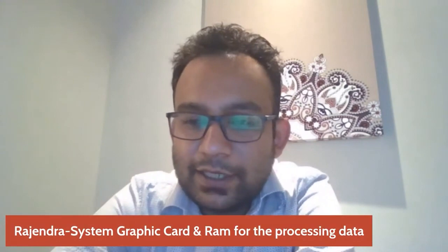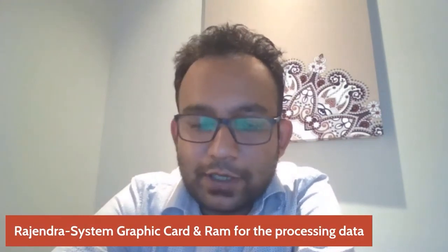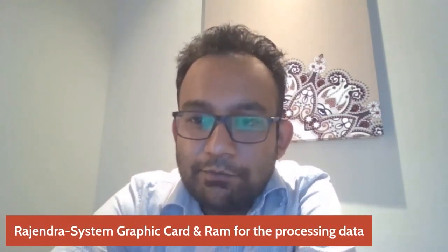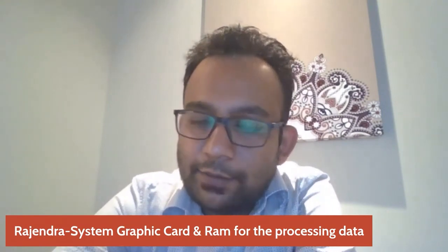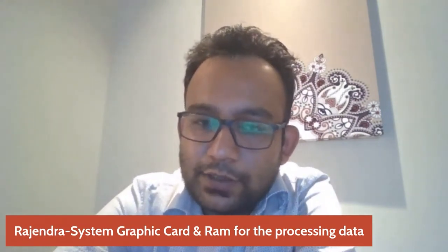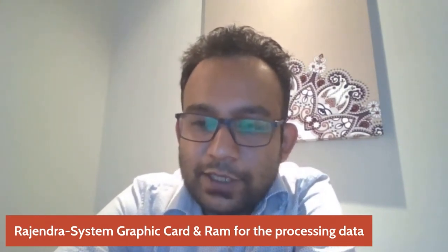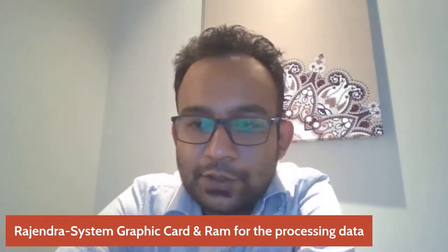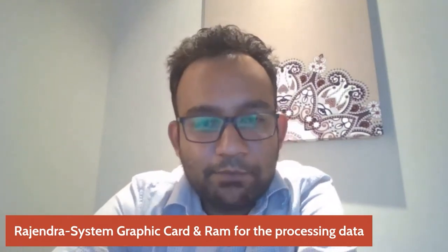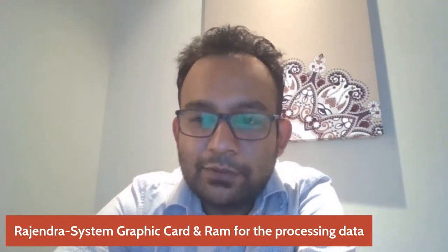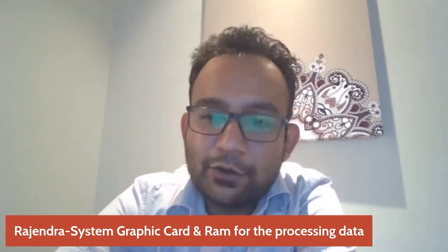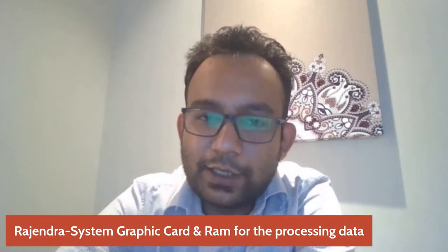Yes, Rajendra, that's a good question: system, graphic card and RAM for processing the data. So Rajendra, my recommendation is to get at least an i9 or Intel Xeon based processor. It should be a multi-core processor, and I recommend a RAM of at least 32 GB, and preferably at least a 4 GB graphic card in the NVIDIA Quadro series. If we can have an NVIDIA RTX based graphic card which will support ray tracing as well, that will be more fantastic. But minimum 32 GB RAM and 4 GB of graphic card alongside a multi-core processor, preferably i7 or i9.